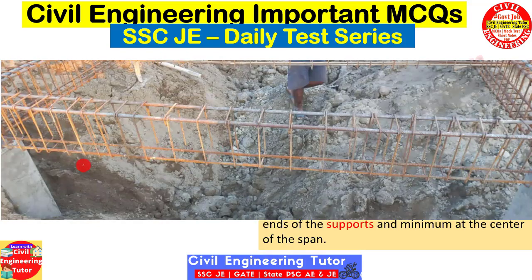Here we can see a typical reinforcement in a site. In this beam you can see these portions are near the supports, but this is the mid section. You can see that the spacing here is more as compared to here.